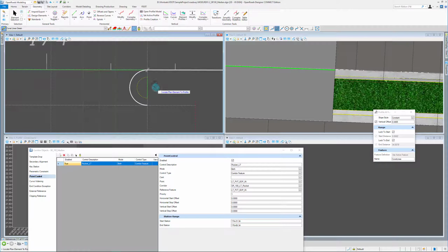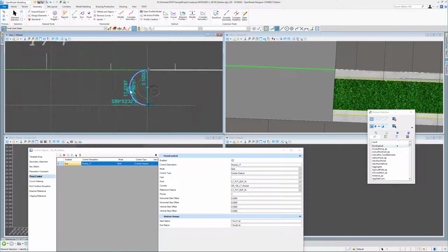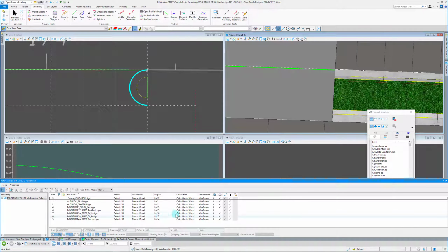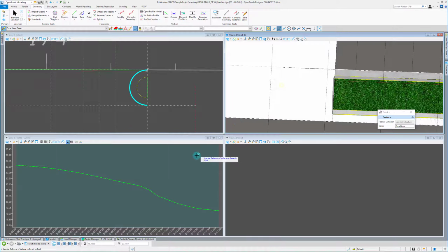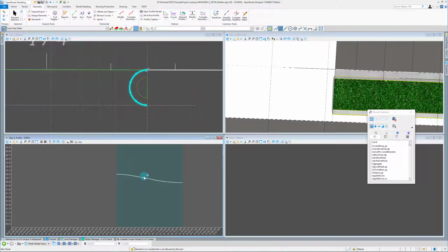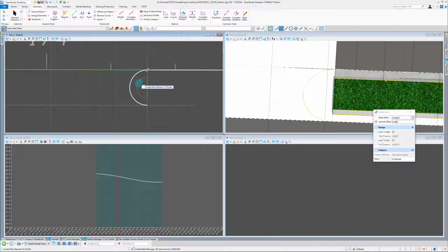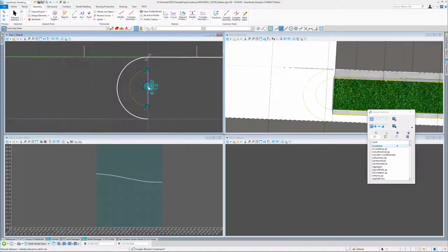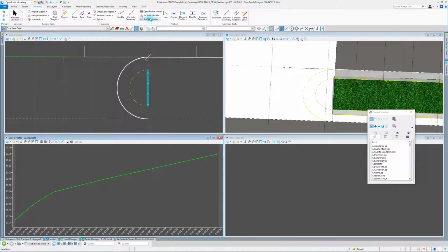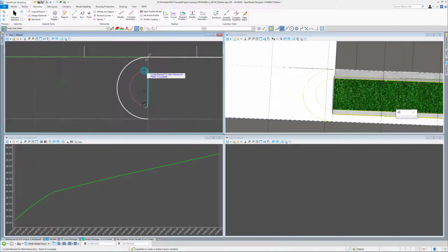So we're going to do our profile again. And actually I need to profile this first. So let's close this corridor. We're going to turn our pavement projected back on so we can grab that. Okay. So see, this one's got a kind of a wavy profile. So you know that's following that. Do the curb, reference element. It's all set from last time we did it. That's great. So then we can model this, do our profile intersection points.